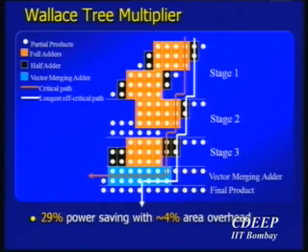Before I go to random logic, it turns out that when it comes to multipliers, Wallace tree multipliers are an interesting example because they are used quite a lot for very fast multiplication, and because that's where you have a tree kind of structure. And when it comes to a tree structure, think about it, you don't really have those path slacks available. So you may not be able to apply any one of these algorithms, or at least the methodologies that I talked about, because most of these paths are more or less of the same size.